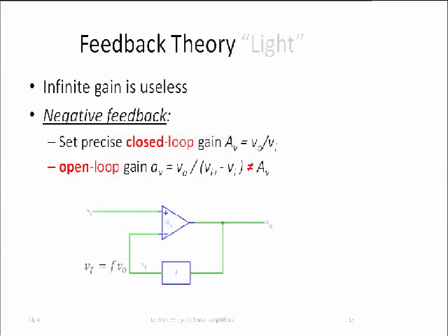So last time we introduced the notion of gain. We need some form of amplification, right? The output from a microphone is microvolts, it's just not going to drive a speaker. And in order to get that gain, we found that there is a component that we can use for amplifiers in circuits. It's called an operational amplifier, or for short, op-amp. Op-amp, right?